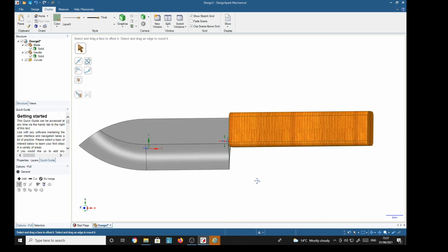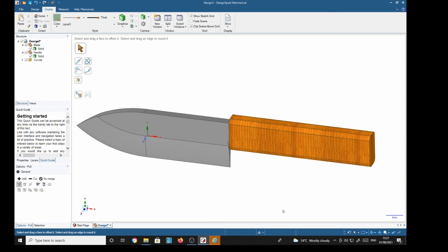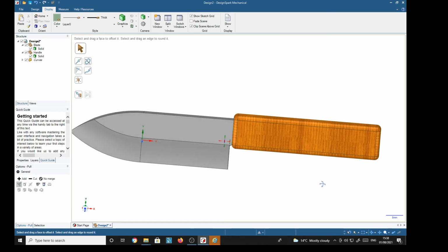That is nice. But we're not finished yet. Double click this edge, hold the control key, double click that edge, make sure we've got a rounded corner, type 2 return, got a curve on that.